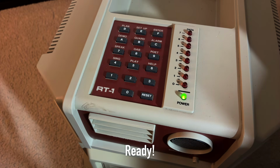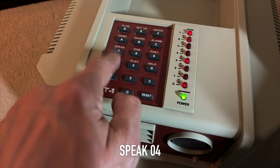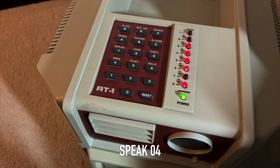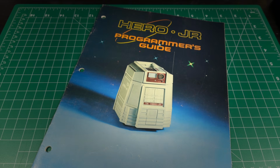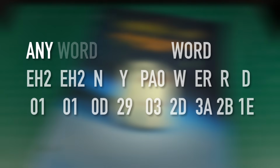Ready. And finally, we can hear the results of our labor by running Speak 04 again. I am RT1, your personal robot. Changing the user's name is done the same way, but its pointer is located at 03C0, and we store its phoneme pattern at 05F7. The programmer's guide has a list of male and female names with their matching hex numbers, but later in this video we'll learn how to encode any word we want from scratch.